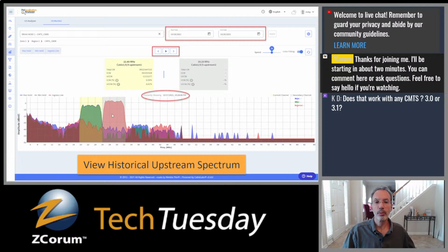So we've got upstream monitor there, and we're looking at max, min, and ingress under the line, as I was showing. And you can put in your start date and your end date, or you can just play or click the buttons to see that. So, all right, that is the basics of PNM. Hopefully this was helpful.